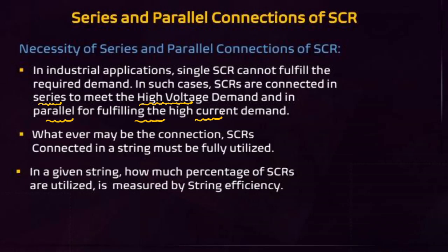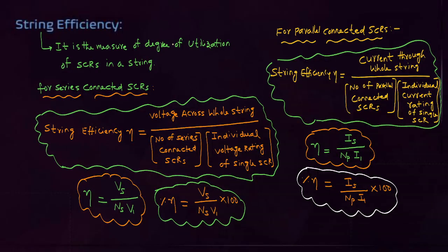But whatever may be the connections, SCRs connected in a string must be utilized to the maximum. How much percentage it is utilized is measured by string efficiency. This is the string efficiency, very important.